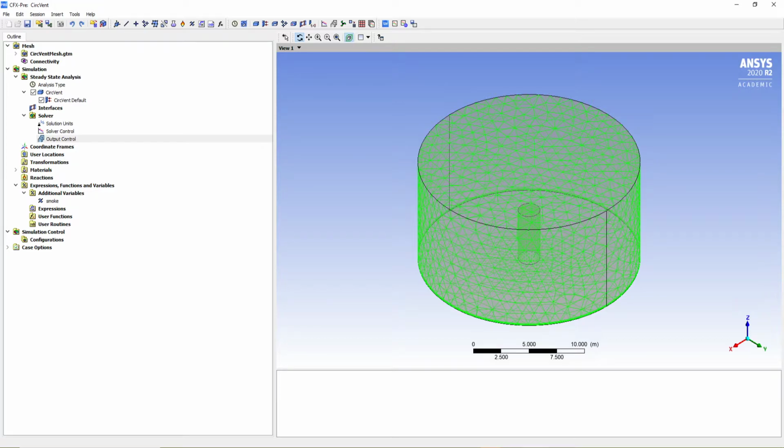Now we're going to create some boundary conditions. For this example we have external flow, since fluid is flowing over an object and not through an enclosed one such as a pipe. In our second and third lectures, we had water flowing through a pipe and reaching the mixer. Now we have a flow going around an object. In external flow problems, some inlets are made sufficiently large so that they do not affect the CFD simulation. This is why our inlet is this whole wall right here. It's a very large inlet, so that it doesn't affect the CFD simulation.